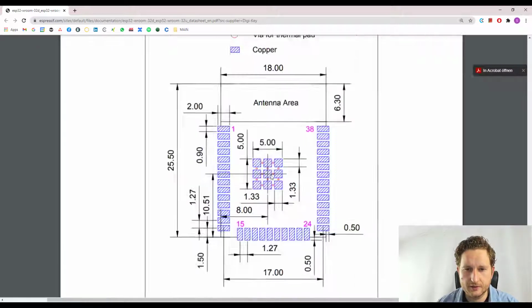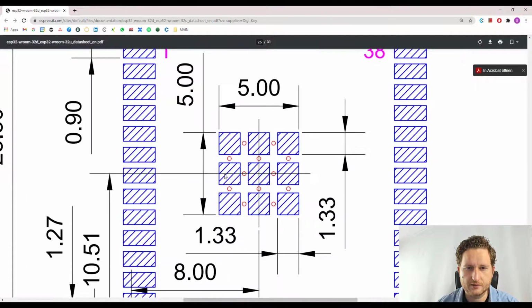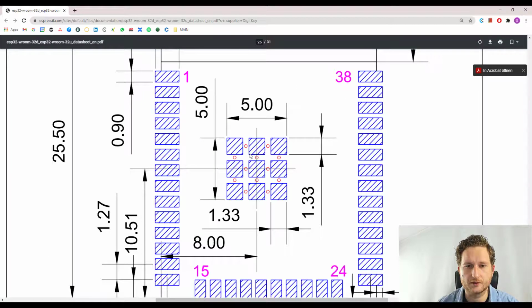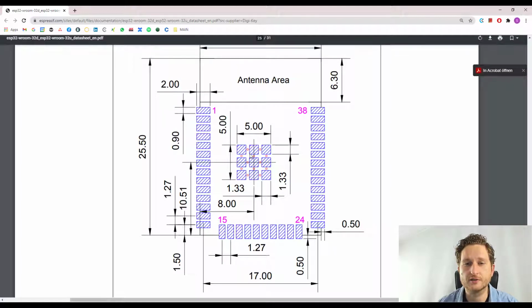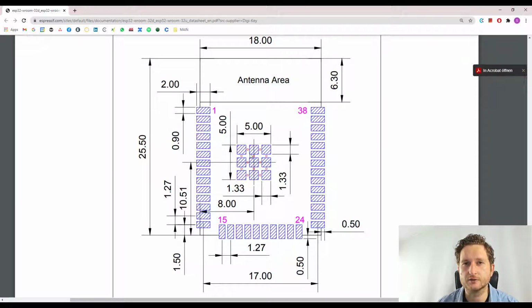As you can see, they have placed the wires in the exposed pad in the middle and in between those pads. But I don't want to place the pads in the footprint. We will place them later during the placement process in the PCB document and when we come to wire placement and routing.